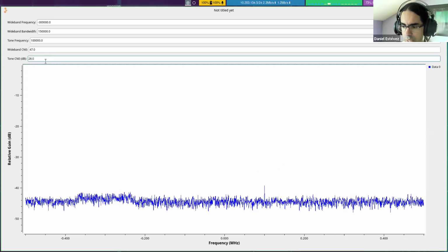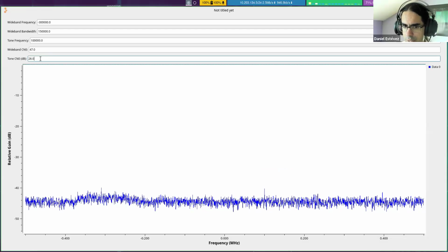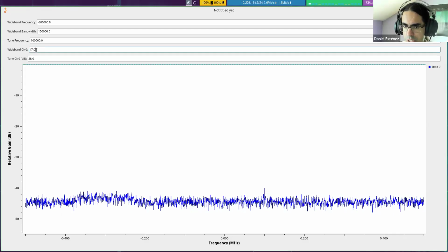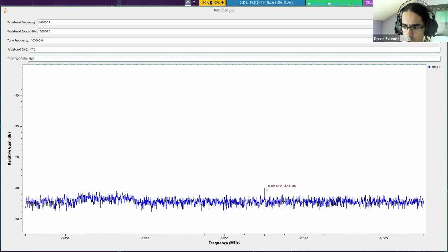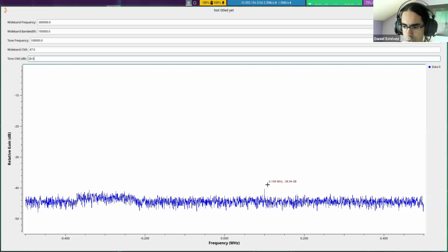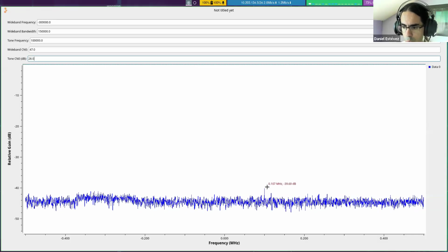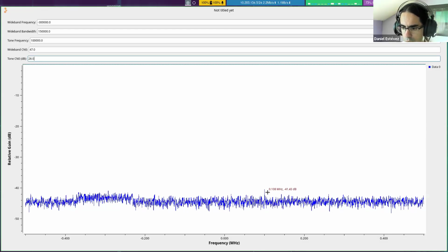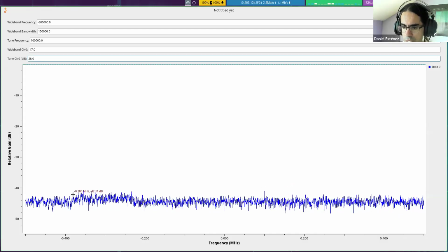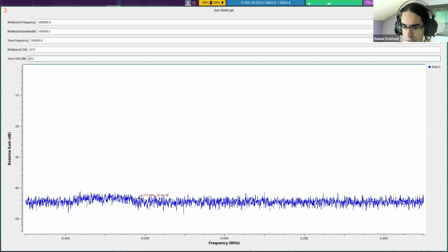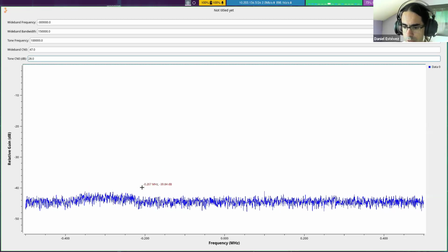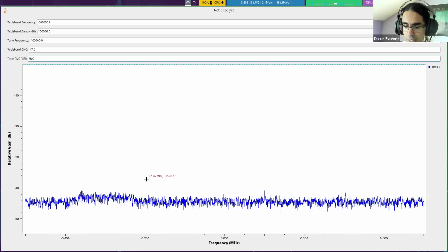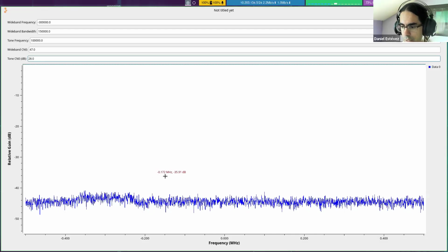So, something we have seen is that the tone can be detected with much less power, 27 decibels compared to 47 decibels. And the reason for that is just the occupied bandwidth. It is much easier to detect narrow band signals because they only occupy a very thin portion of the spectrum, and we can see the signal, all the power is concentrated there. Whereas with these wideband signals, the power is spread over a large portion of the spectrum, and we cannot do anything smarter to detect them unless we know additional characteristics of the signal.